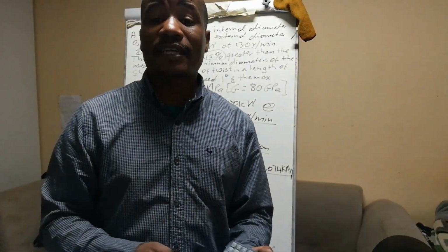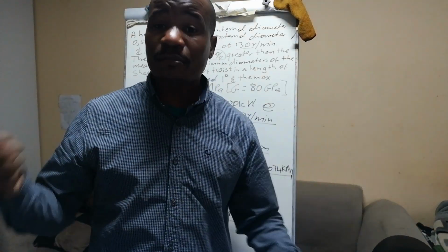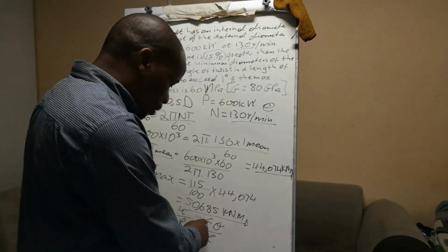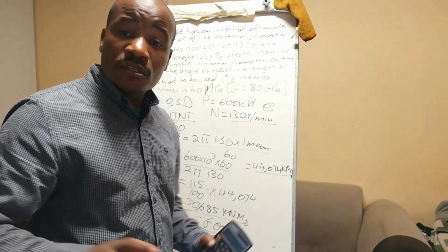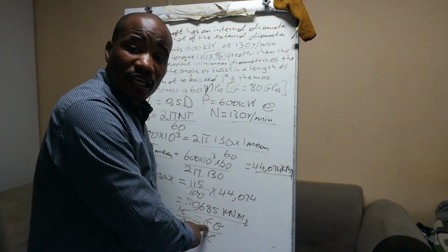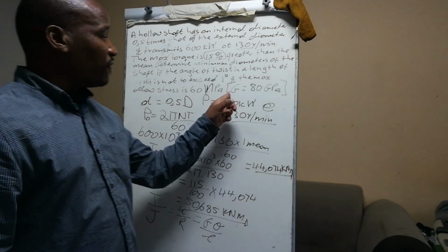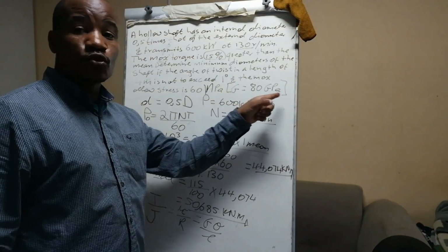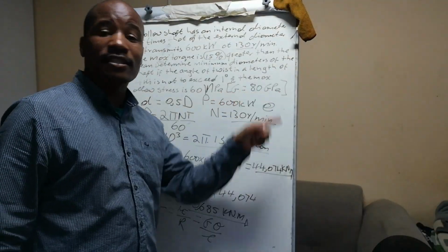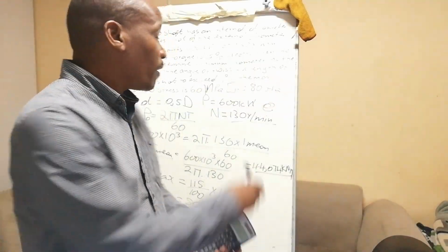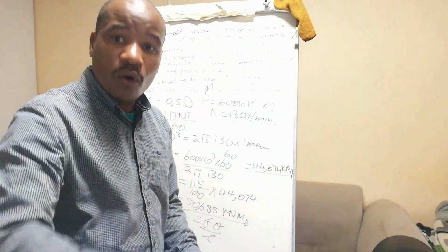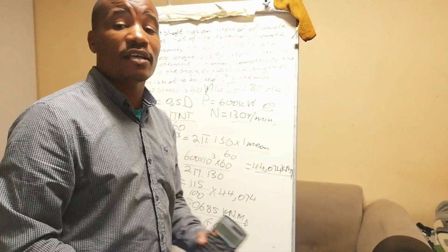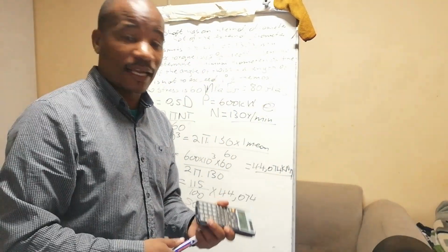It is the strength of that shaft if such and such material has been used. Basically, that's the case. So the modulus of rigidity is one of the values that you'll have to find from a table, or the manufacturer will list it. In the academic book, it is listed. That is why they told you that G is equal to 80 gigapascals. But in the field, you have to find it from a table, or call the manufacturer to ask what is the modulus of rigidity of this particular shaft. But that is a discussion for another day.